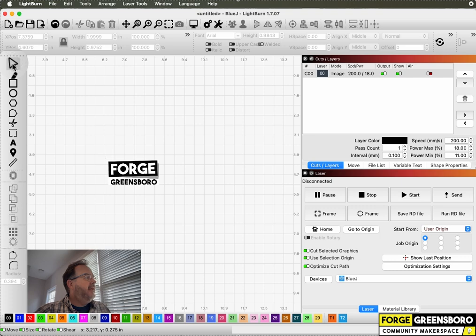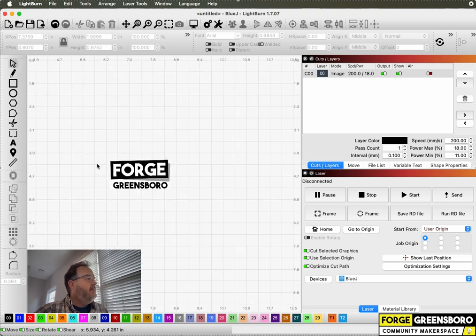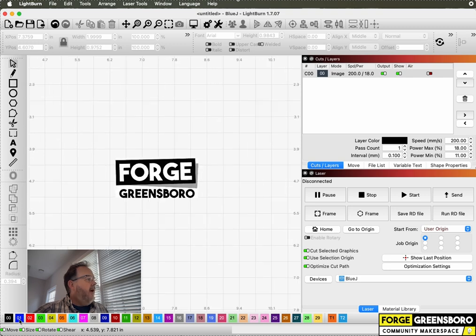I did that by selecting my selection tool and clicking outside here somewhere. Zoom in a little bit more. I'm then going to choose my 01 layer, and I'm going to draw my circles and ovals on that layer. So, selected 01, have my ellipse tool selected, and then going to draw out an oval.